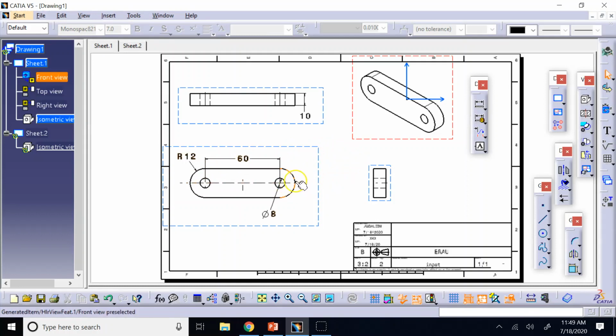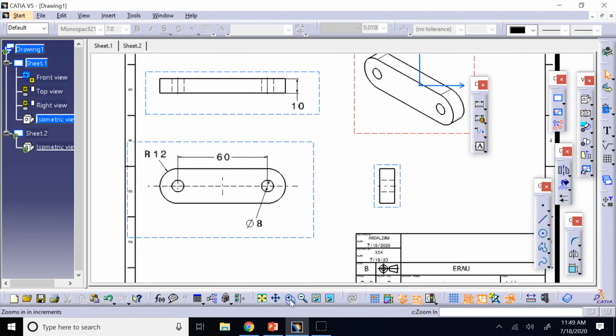Instead of providing the end of the arc to the end of the arc, which I said you should avoid, I provide center to center. Do not go from the right edge of this arc to the left edge of that arc. That's not a good way to provide it. So now I have the overall height, the overall length or width, and the overall depth. Now about a feature like a circle or a hole.